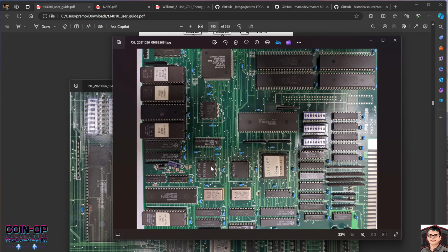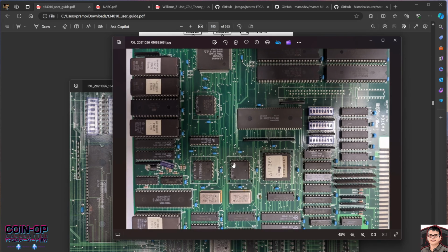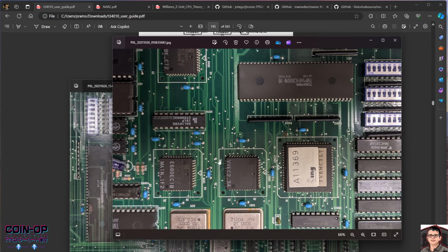Sometimes I have different probing clips that I use. For example, this chip is a chip that I've traced before. I have a clip that goes on this that makes the probe pins bigger, so I can attach signal probes, logical probes, to see what the signal looks like, so I can get the data output from this and see what it's potentially doing. So I do attach probing clips to each of the chips I need more information on.